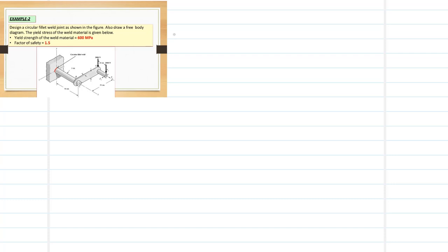Now, first find the stresses due to P1 equals 2000 Newton. So let's say first find tau D1. Now tau D1 is basically the direct shear, which is nothing but P over A. The simplest formula of tau D is P over A. Now P is equal to 2000,